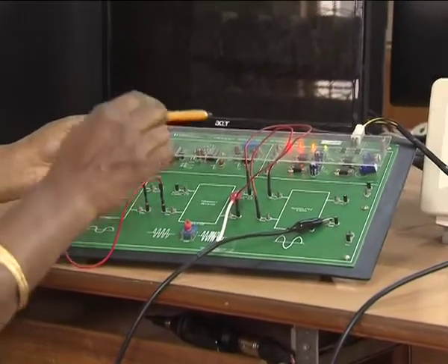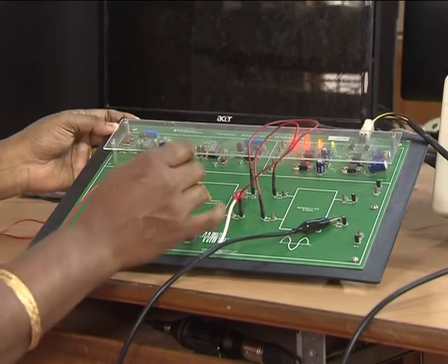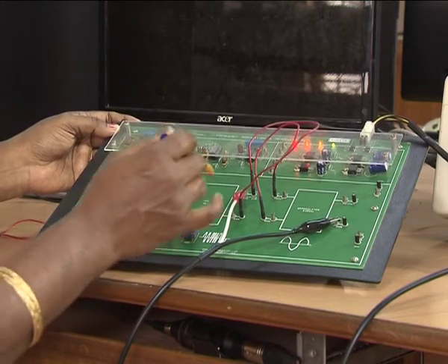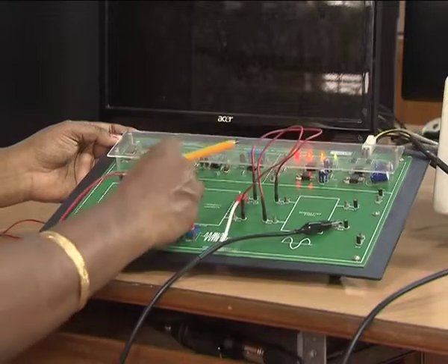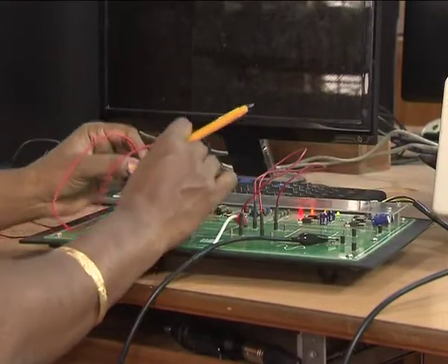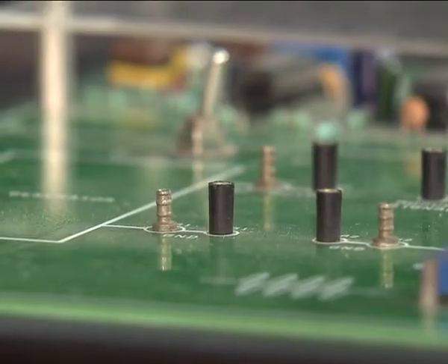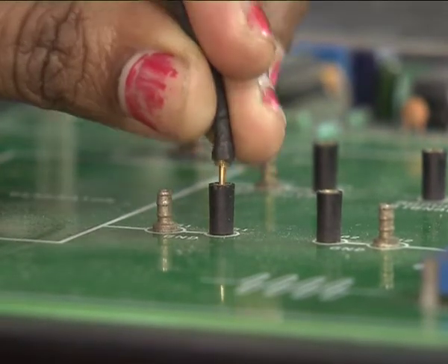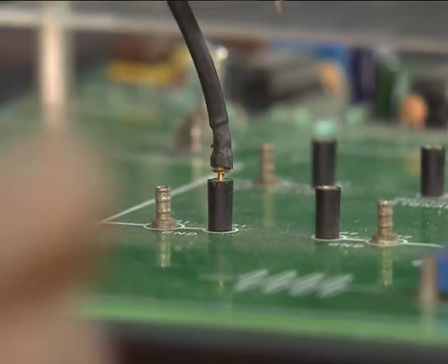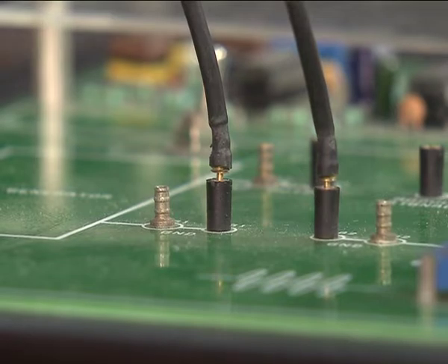This input signal is to be fed to the frequency deviator, which is a voltage controlled oscillator that will generate an oscillatory waveform with respect to the amount of voltage we provide at its input. First we have to connect the ground. These are the ground pins which are to be connected. So, first we should provide an input, that is your modulating signal, to the frequency modulator. Now I am connecting the ground pins using the patch cord and then I am going to give the input.